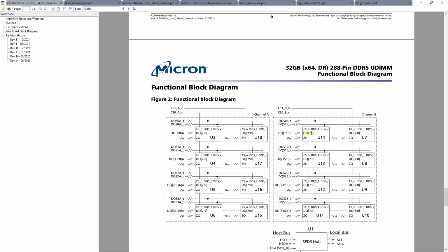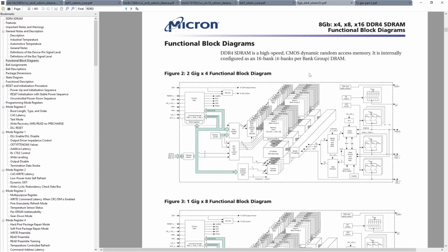So the capacitance of the inputs, the extra wire that connects the memory chips to the memory controller. And to be fair, the memory chips in multi-rank configurations do have termination resistors to minimize reflections and that kind of thing, but that still doesn't change the fact that you are just putting more and more load on the memory controller the more memory chips you connect to it. So with DDR4, going from dual rank to quad rank is basically a performance downgrade.